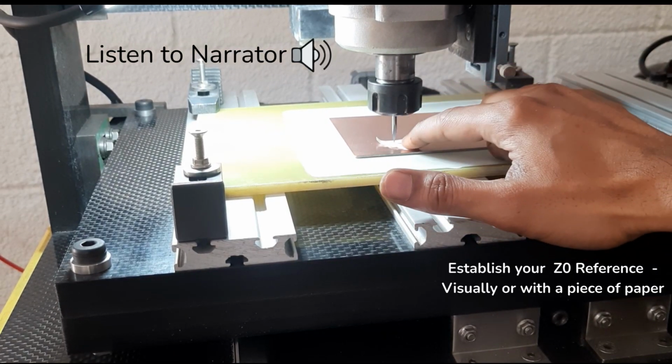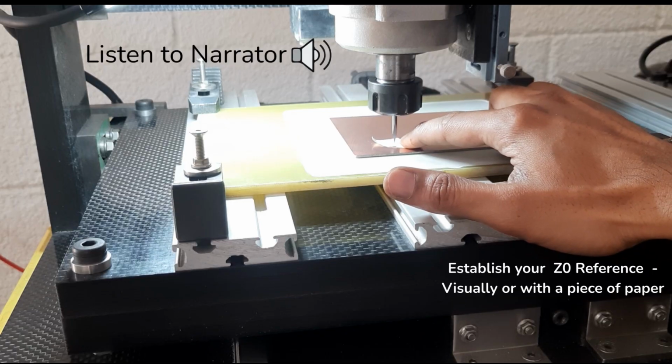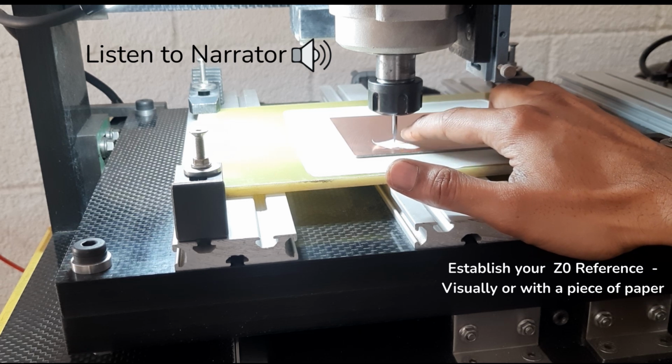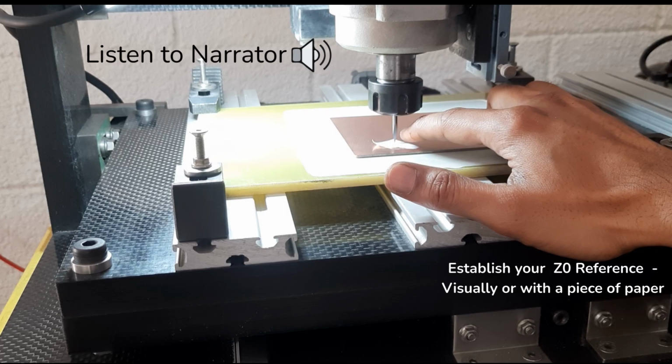You can lower the Z until there's enough space for a piece of paper to go in between the bit and the copper clad. Further adjustments we can try. So this paper is about 100 microns thick, so we can reduce in 50 micron increments until we get the bit to start engraving on the PCB surface.